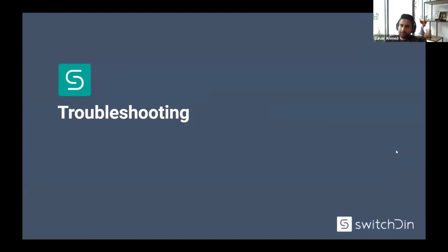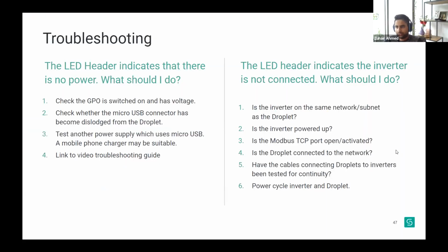All right, just a few troubleshooting steps. The LED indicators for Droplet 1 are a good place to start troubleshooting the device. In case the LEDs don't come up, power cycling the Droplet could help. There are 2 tiny LEDs inside the Droplet 1 case. If they're not running, then that could also mean the Droplet processes are not running.